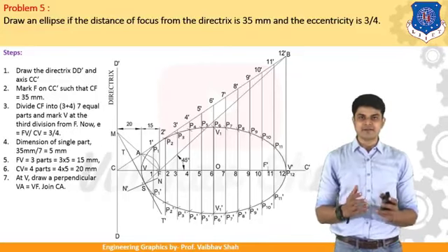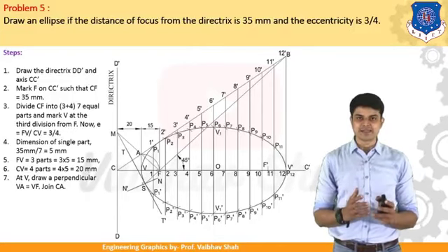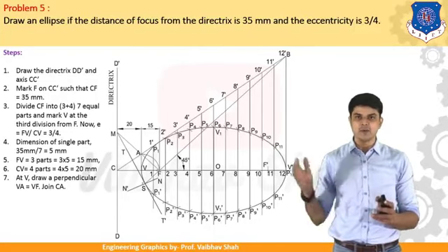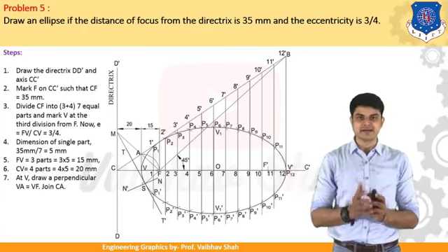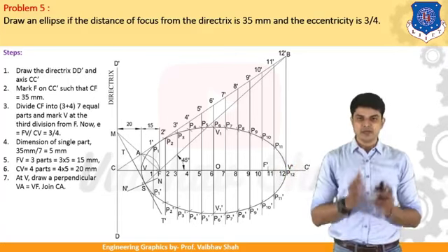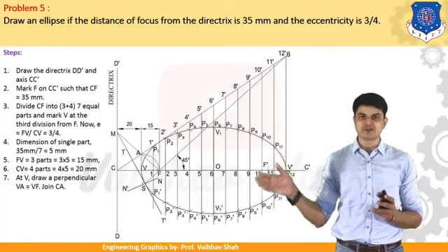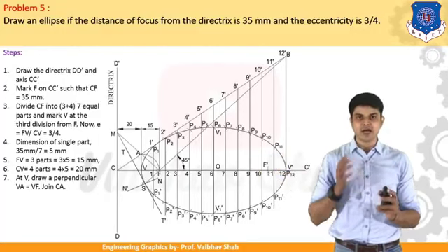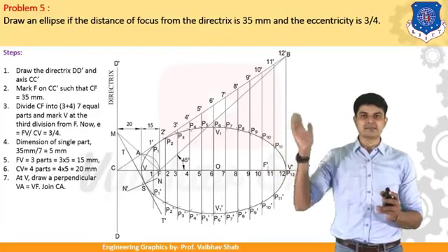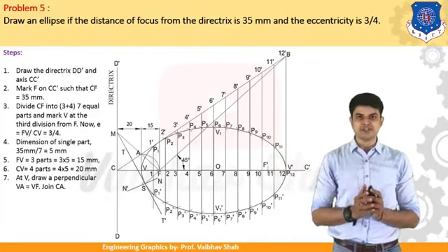So now, after dividing the line into 12 equal parts, number the points on the horizontal line 1, 2, 3, 4, 5, 6, 7, 8, 9, 10, 11, 12 onto the right hand side until you reach the V dash. Then after let us draw a vertical line from each of the points like this. So we will be constructing vertical lines from each and every point like this until we reach the inclined line of AC.